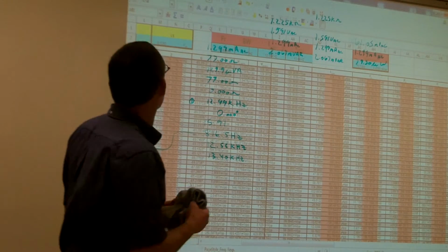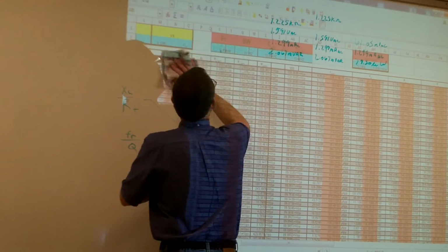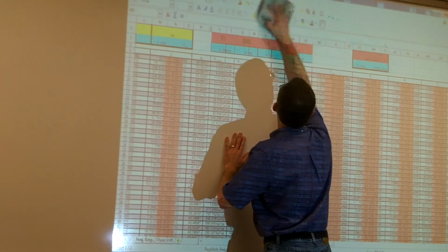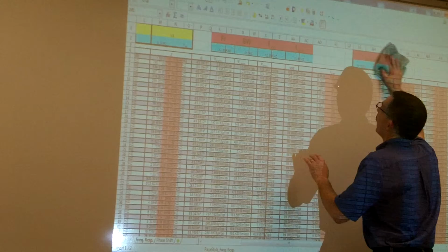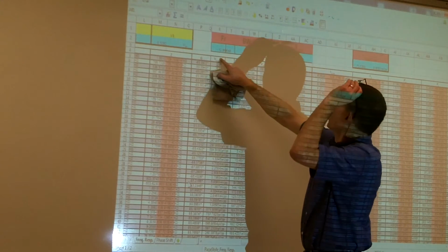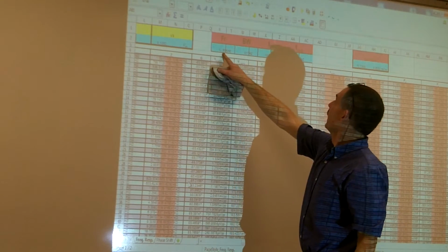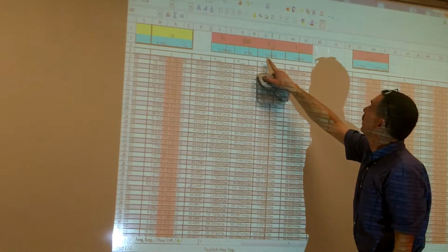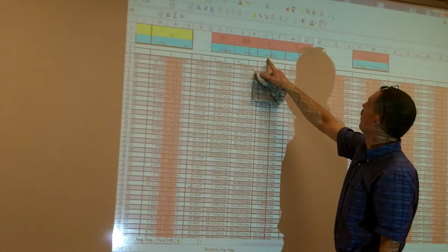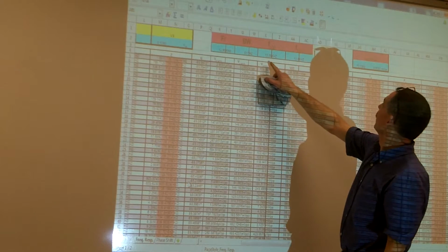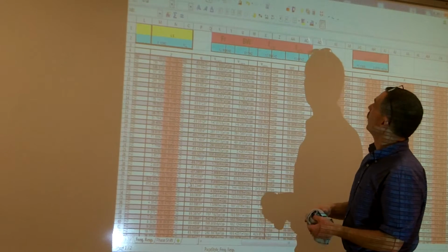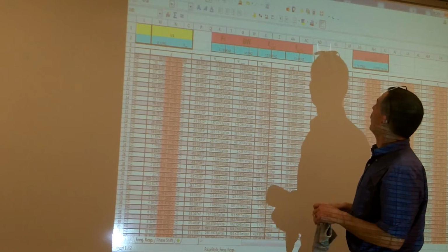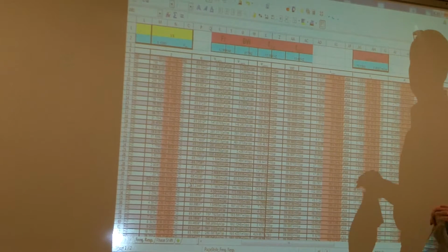So if I put these numbers into my spreadsheet here, you can see we end up with the same resonating frequency, 12.99 kilohertz. I had a bandwidth of 817 hertz. My lower frequency cutoff was 12.5 something, I can't quite read it, 12.5, and then 13 point, what was it? 5.8. And then 13.4 kilohertz for our upper frequency cutoff.